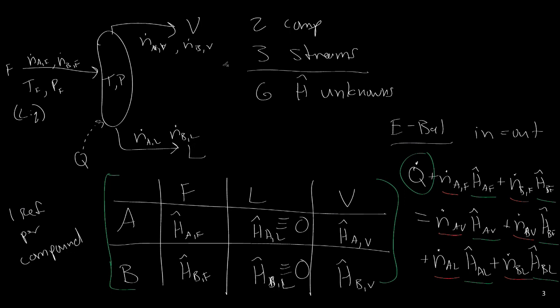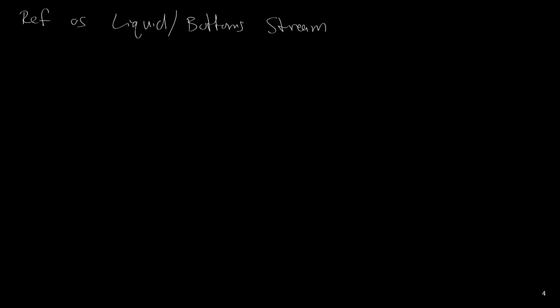Going from the liquid to the vapor stream, we are at the same temperature. All we're doing is changing the phase. So if we have a means of estimating the heat of vaporization at the system temperature, it only involves one calculation going between the liquid and the vapor enthalpies. Hopefully the rationale behind that will be a little more clear once we work through the calculation.